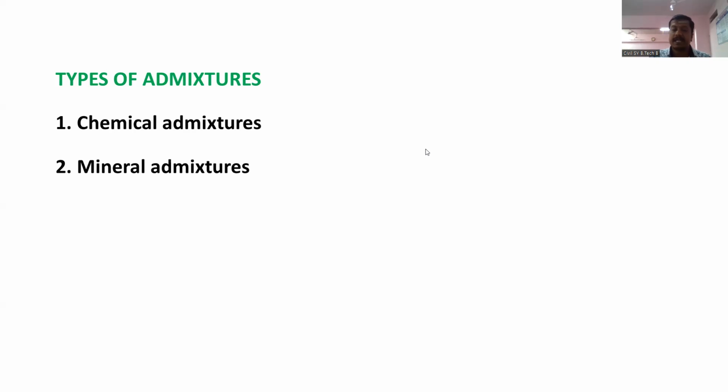Okay, so chemical admixtures, we are having plasticizers, super plasticizers, air entraining agents. Air entraining agents are nothing but those which help us to improve the workability. We are having gas forming agents, accelerators, and retarders.